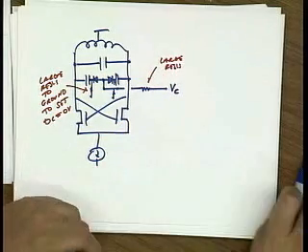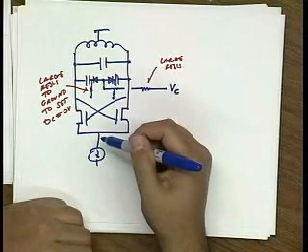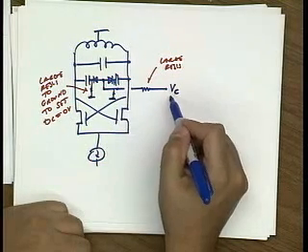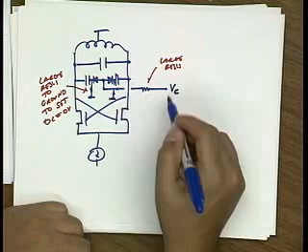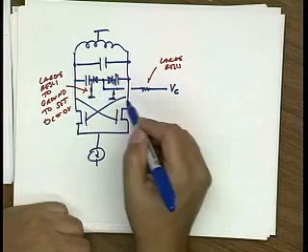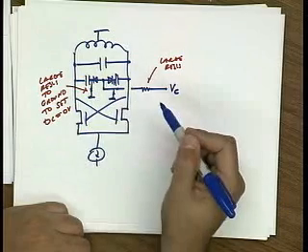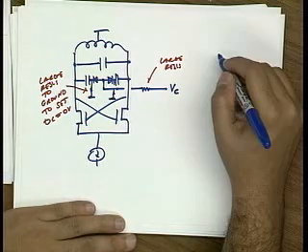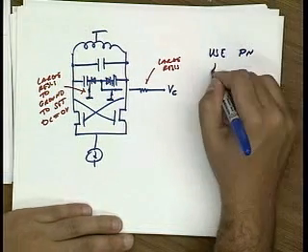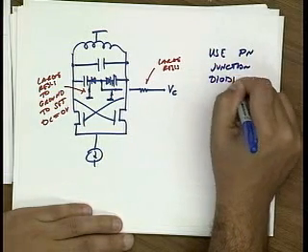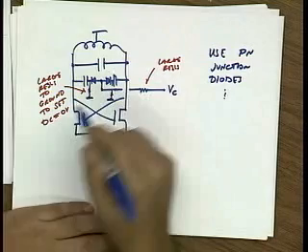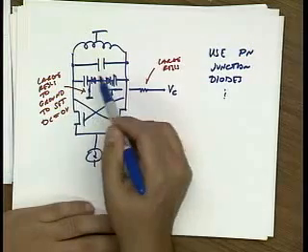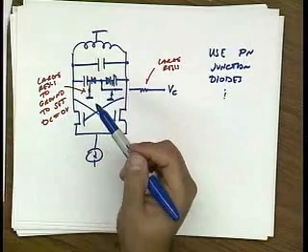The idea is that I'm going to change this control voltage, and actually this should go to VDD in this case. If I go to VDD, then the forward bias is equal to 0. If I go to 0, I have maximum reverse bias or minimum capacitance. So I can vary the capacitance of these diodes by changing the bias here. Using PN junction diodes is one way to go. In the last lecture, we talked about the parasitics of a PN junction diode. And again, we can see the advantage of hooking them up in the right way so that the parasitics end up at the virtual ground.